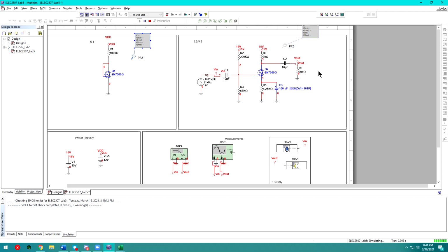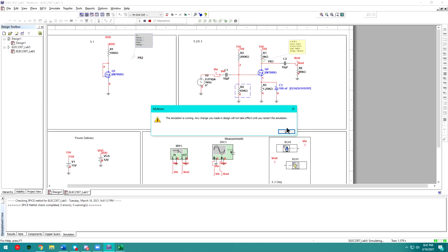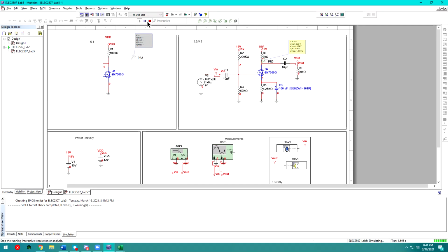Now we're running. And now we can actually place this voltage probe on the drain, and see that my VDC isn't close to VDQ. Well, it's somewhat close, but it's not as close as it could be. So now, this is when you actually adjust R2 to get it a little bit closer to VDQ. So I adjusted to 59k, and I ended up with a VDQ of around 7.47, which is very close to 7.5, which is nearly half my supply, which is exactly what we're looking for.